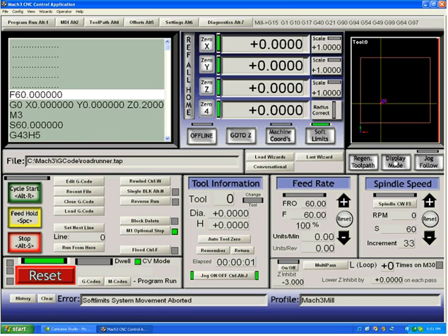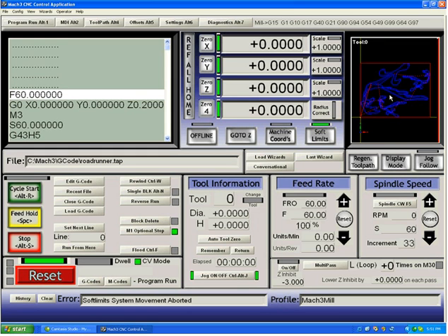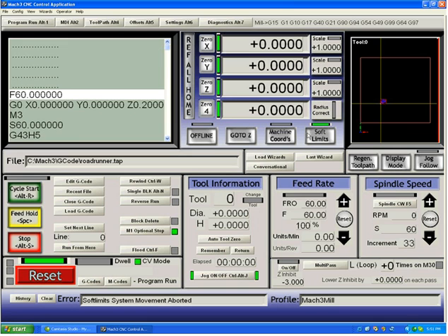and recutting the job. This display mode tool can be a valuable way to see where you are in a particular offset system. Here in G54, we know that we're going to cut this job at this location, and this location can be seen by checking the machine coordinates button.